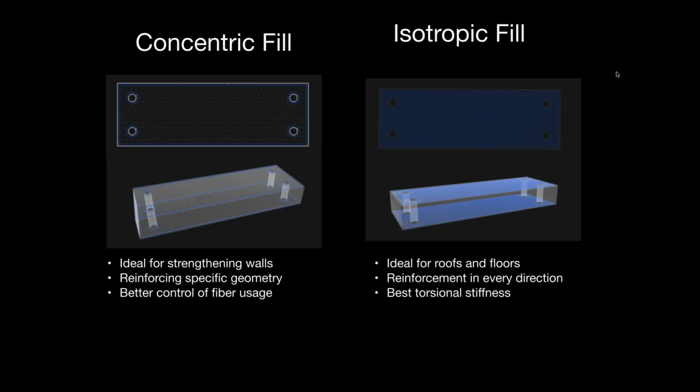So that's going to be just good practice in terms of reinforcing a part that's going to undergo flex. You can imagine that if I try to provide a bending moment to this part as it's reinforced right now, it's going to be kind of like an I-beam, and the top section and the bottom section are seeing the greatest stresses. So you're going to be seeing the biggest stress concentrations at the top and the bottom of the part. So it's generally best practice to use what we call sandwich panels and reinforce the part at the top and the bottom.